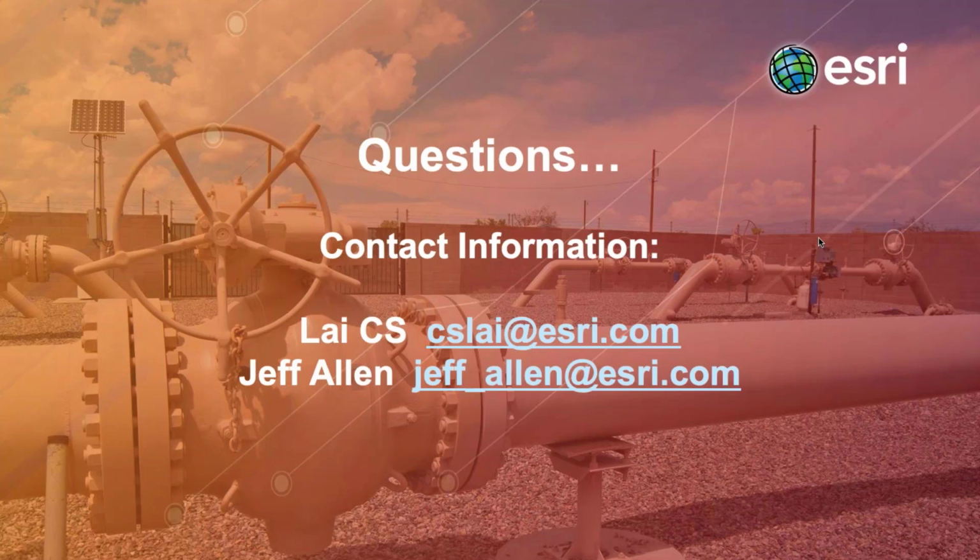Great. Next question is, can we set rules with another layer, for example, pipe with electricity network, and how to do that? Yep, absolutely. So one of the ways that the utility network is quite interesting is because we have the ability to have what we call domains. So I was demonstrating the pipeline domain, but multiple domains can exist in the same geodatabase. So you could have a water domain or an electric domain that has different rules and different components using that same cadence of connectivity, and then you can actually trace domains together.